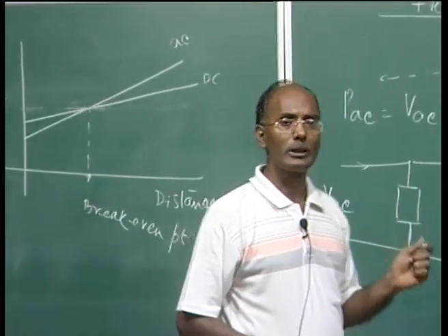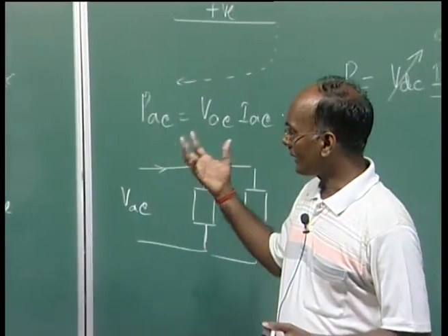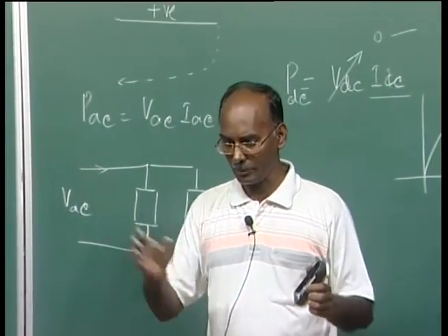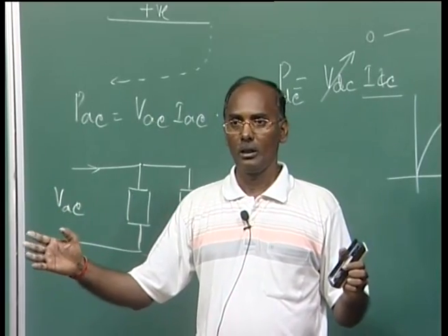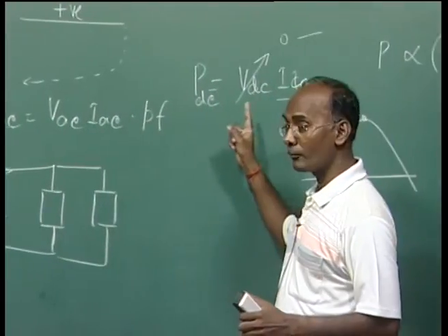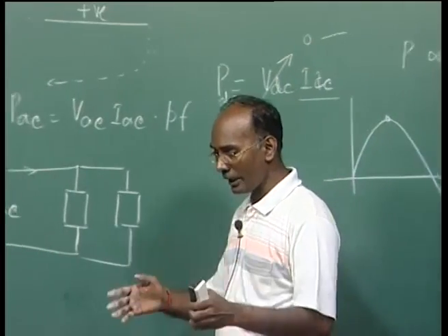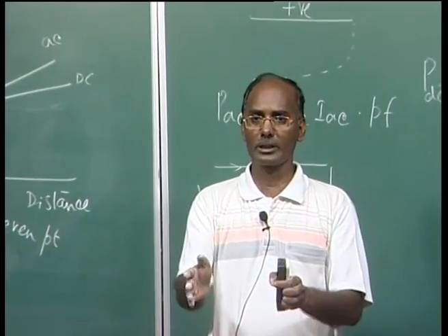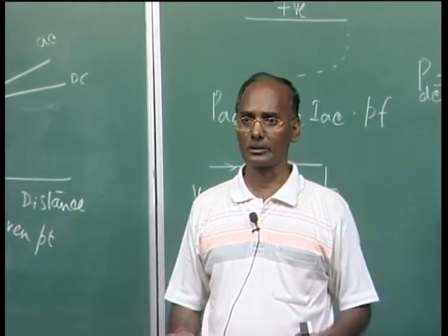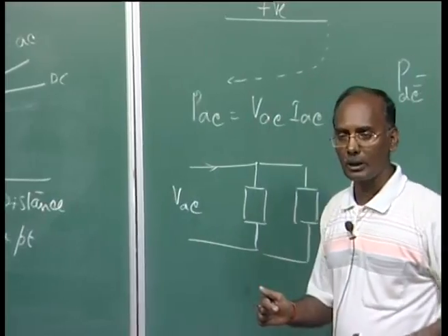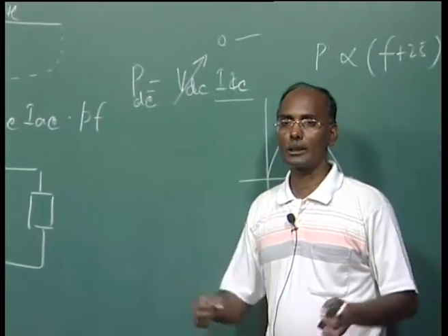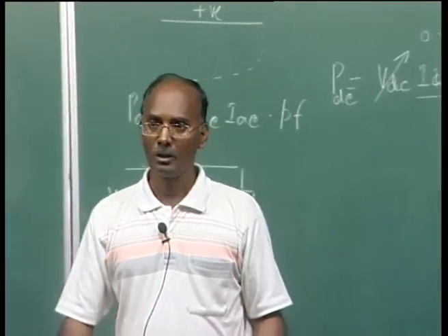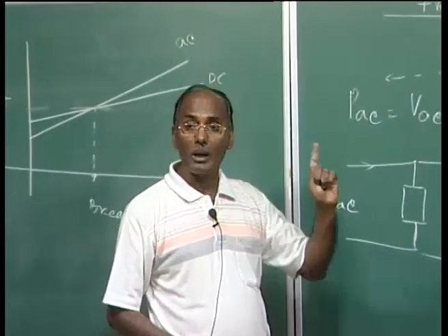But nowadays this is not only true, because the HVDC system is not only used to flow power from one distance to another. One advantage of DC, as I said, is power flow control. Sometimes we require power control from one area to another area. The distance is not large, but a boundary is there, so the distance may be 10 meters, maybe 1 kilometer. For that purpose also, we are now using the DC system, and that is called back-to-back connection, meaning the converter and inverter are in the same substation maybe. So the intention is to control the power only.